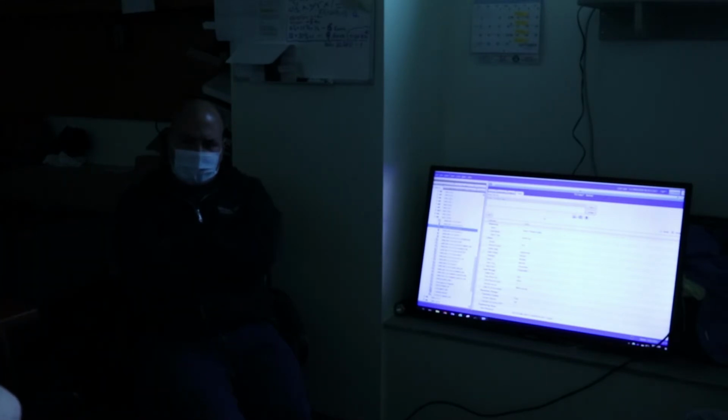How is that? You're talking about making an adjustment at the air handler or making an adjustment at the VAV box? Mostly, I don't know how the air handler in a new building will work, but on our older system, what we have here for CSB, it takes a long time to get the adjustment if we change the set points for temperature, for example. The discharge air temperature of the air handler? Yes. It takes really long. Maybe did he change something now that we know? We still have the same.